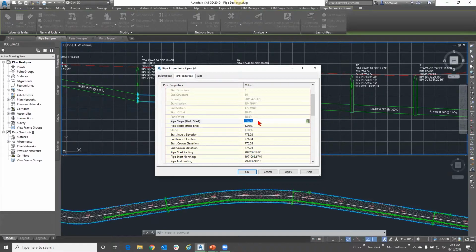Because you always could run into the possibility of fat fingering, and I just did this 2 days ago, instead of putting in an elevation of 125 feet, I accidentally put in an elevation of 1,025 feet. And when I built my surface, lo and behold, I had a huge hill in the middle of my site for no reason, because I went too fast.